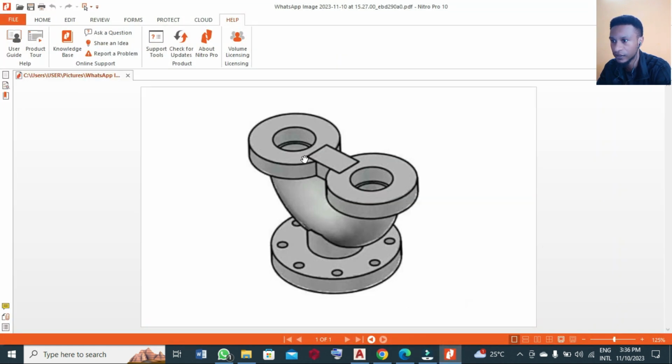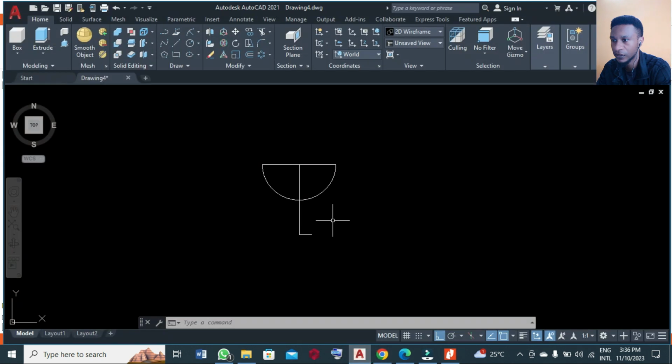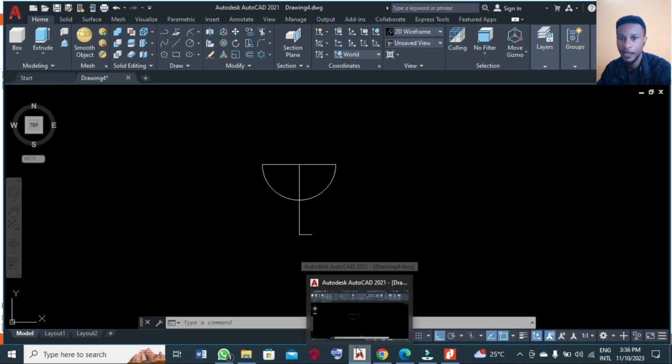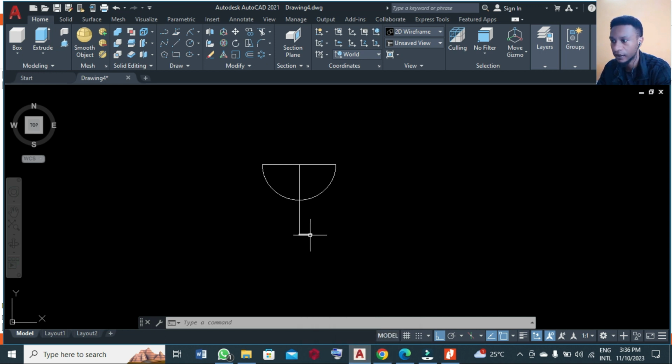If you check this drawing, you see that at the curve like this, there is a T, like a vertical pipe there. So this line will now serve as that vertical pipe. And now, that pipe has an internal diameter, right? So this line here with a length of 32 will serve as the internal diameter of that pipe. Okay. So now I'm going to make a rectangle.